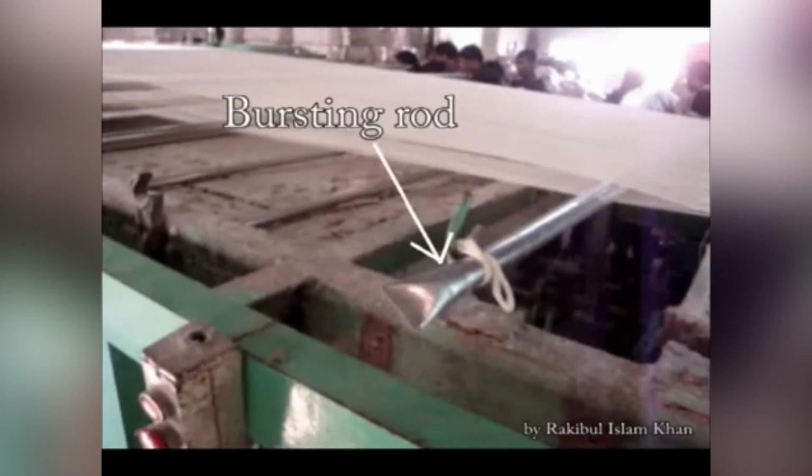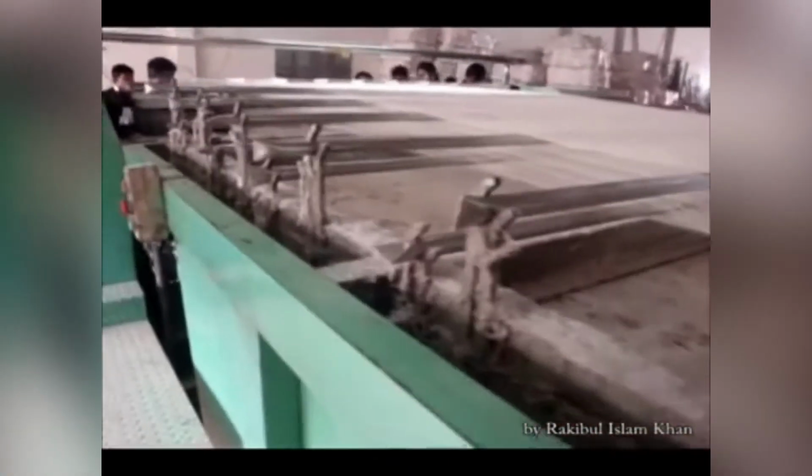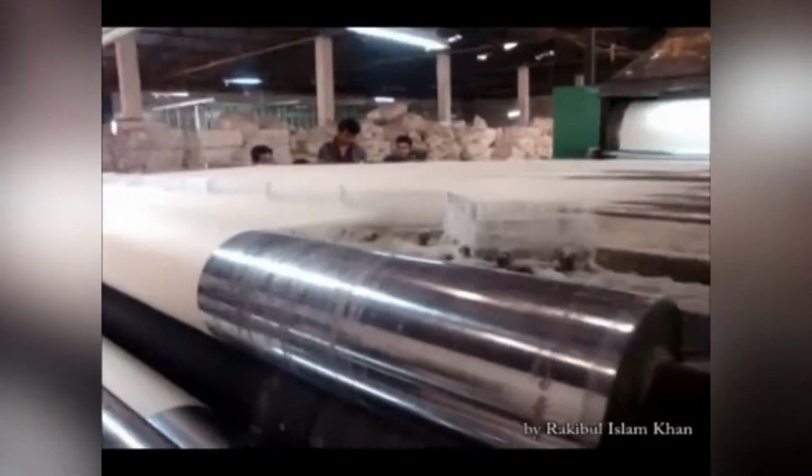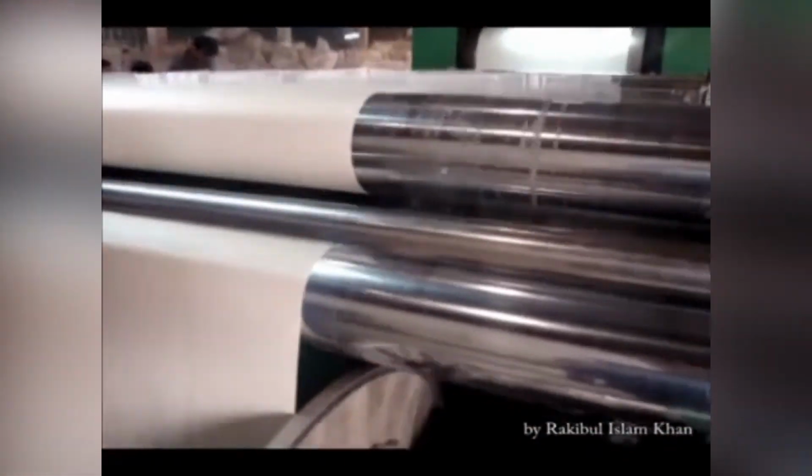After the drying unit, the yarns are passed through the separating unit. Here, with the help of lease rods, the yarns are separated. Then all the yarns are passed through the V-reed and set on the beam, maintaining the warp yarn per inch or ends per inch required in the final fabric. This beam is called the weaver's beam.